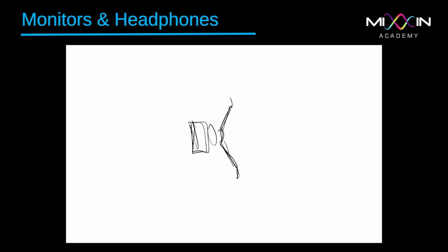People use really light materials. Now, what else? Well, we would have to have this membrane really, really stiff. So it should not wobble, if you know what I mean. So once we move it outwards, the complete surface should move outwards at the same time without wobbling. It would make the sound front incorrect. Now, it means that it wouldn't represent that music accurately. So we need it super stiff, super light, so that the dynamic response of the speaker would be perfect.